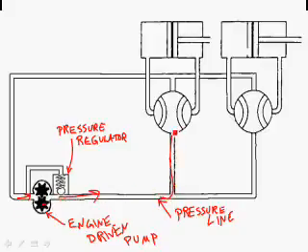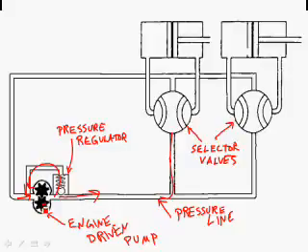And right now, of course, here's our selector valves. And right now they're in the off position, so the fluid can't go anywhere. So the pressure is going to build up here. The ball will get pushed out of the way, and fluid will go around and around in a circle, because the engine-driven pump cannot be disconnected from the engine in flight. There's no switch or lever that you can flip in the cockpit to turn it off.